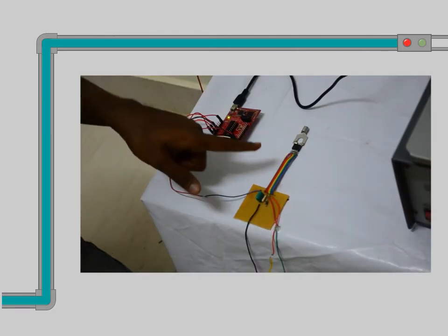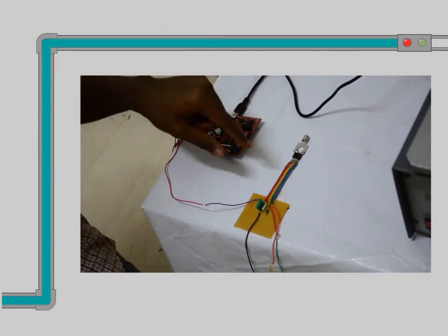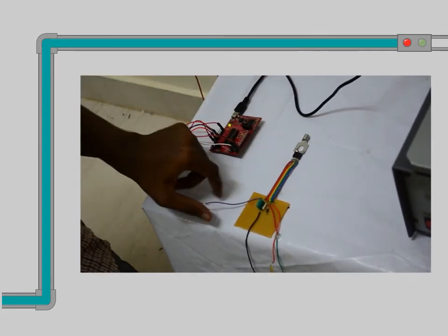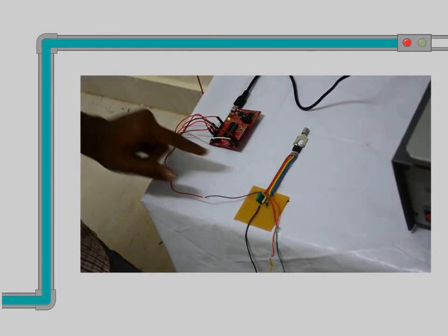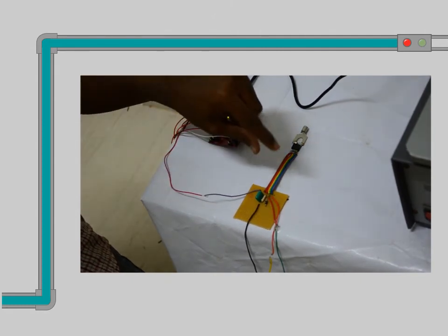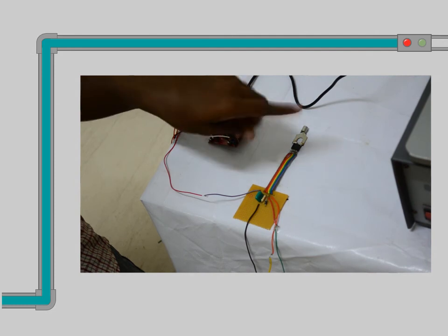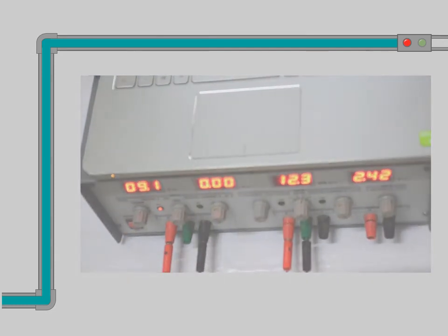This is the DRV101 circuit provided by Texas Instruments. Here we are using it for driving the solenoid valve. The input of this pin is given from the MSP430 through pin 2.4. A potential difference of 9 volts is applied throughout this circuit. At last, a potential difference of 12 volts is given to the solenoid valve.